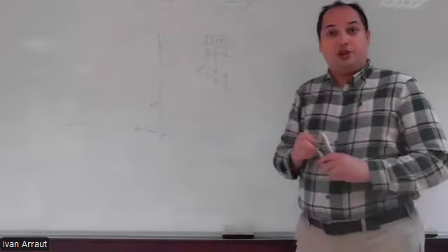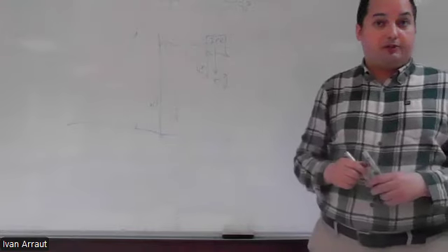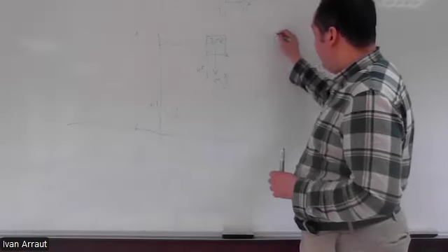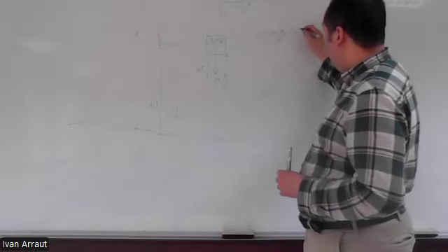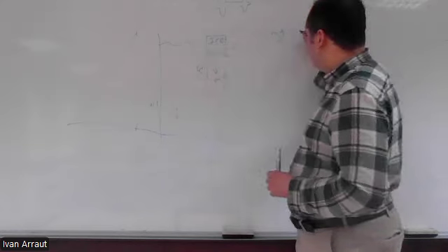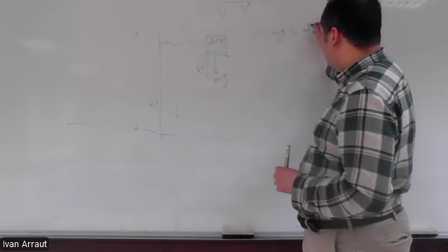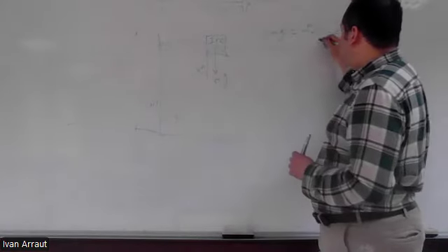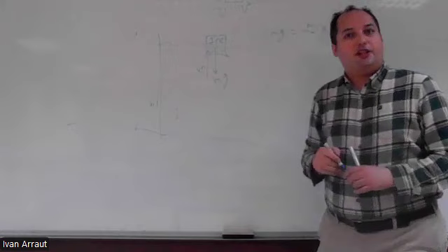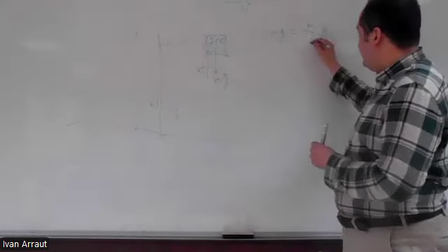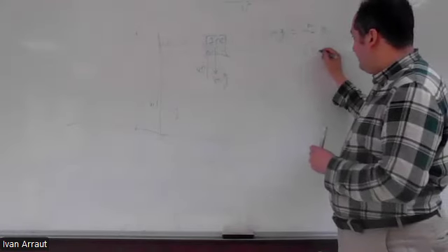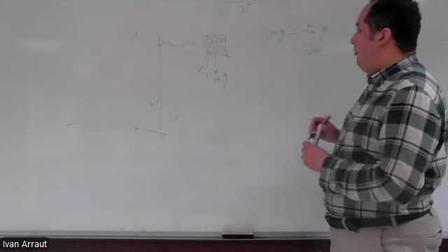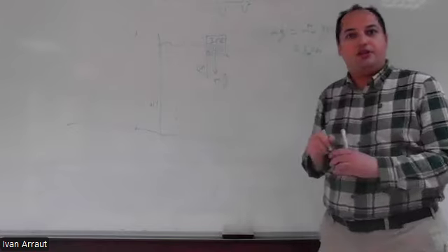This buoyant force is equal to the weight of the fluid displaced by the object. In other words, if I want to make the equilibrium of this, it will be mass times gravity of the ice equal to the mass of this water displaced, which will be this volume multiplied by density times gravity. This equilibrium, and then with this, because this is density of the water, sorry, times volume displaced, you can know what's the percentage.